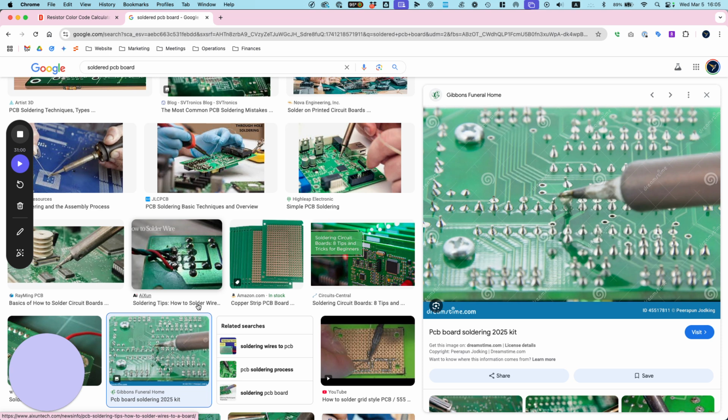Okay, so let me solder that again. So I'm placing it flat down on the surface because I want it. Oh, I lost it again. Let me make sure I lined it right. Okay, good. I want it flush. Even that doesn't look good. Maybe I want to do it on row 13. I'm going to leave 2. Okay, that's better. Row 13, you see it's flush now? And the LEDs, they're pointing in the right direction? Okay, good.